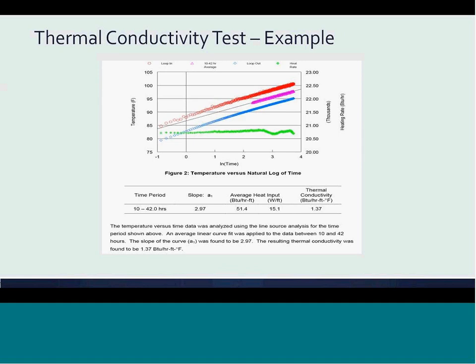This is because we want to make sure any heat of hydration or anything that might be tied to the drilling process is not allowed to give false readings in the thermal conductivity test results. An apparatus like the one shown in the previous slide is connected to the test loop. The test loop should run a minimum of 36 hours and really no longer than 48.